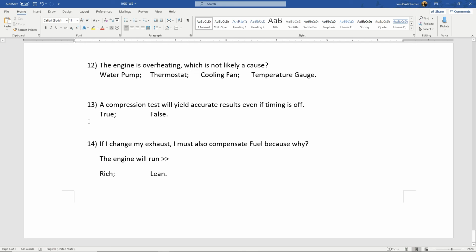And I put this on here. Nobody ever thinks about this. The first thing you should buy to put performance on your car is software to change the computer. Okay? It's very easy to put a cold air intake on. Now we have way more air. It's very easy to put exhaust on. Now we have way more air. But the computer doesn't know to tell the injectors to spray more fuel. And then it runs lean.